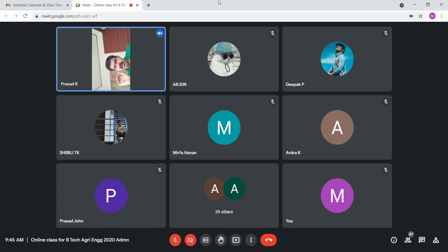Please note, module is the ratio of the pitch circle diameter in millimeters to the number of teeth. It is usually denoted by the small letter m. Mathematically, module m is equal to capital D divided by capital T. That is very important. Please remember module.